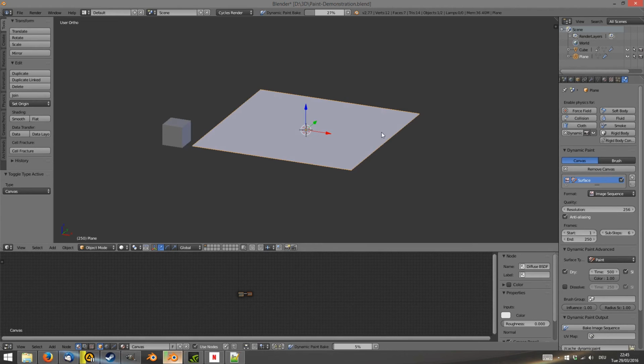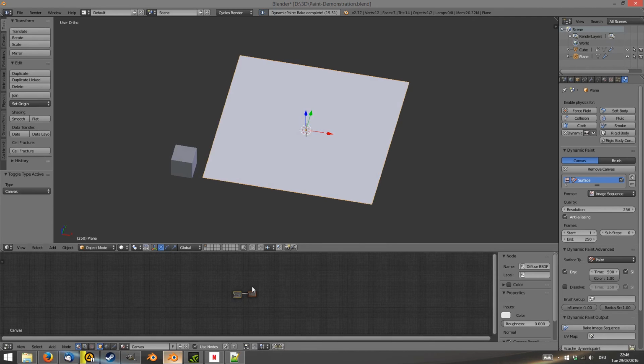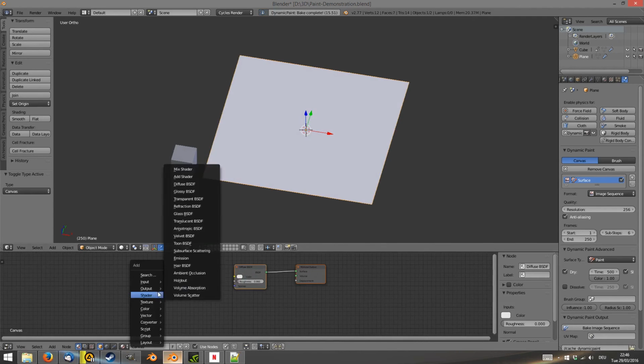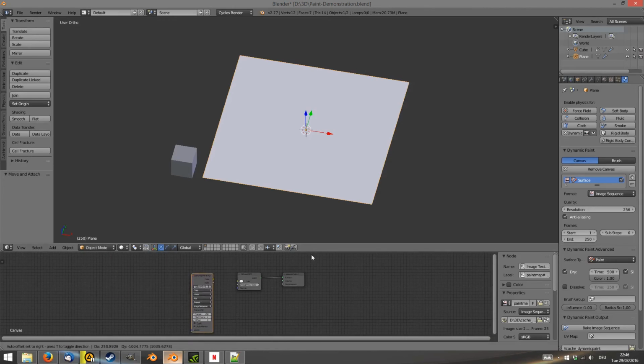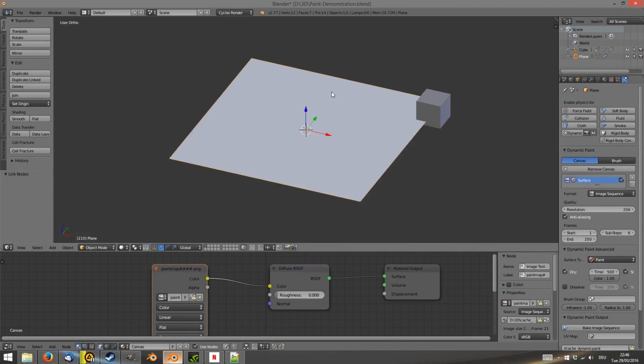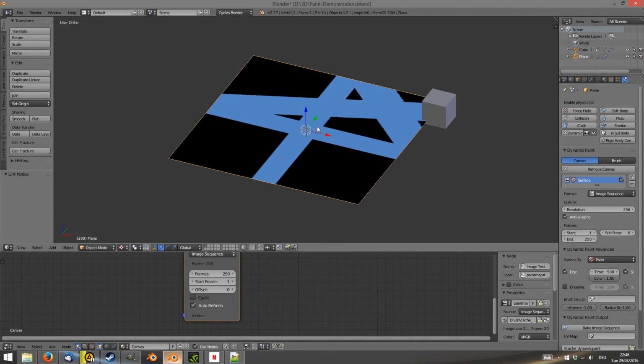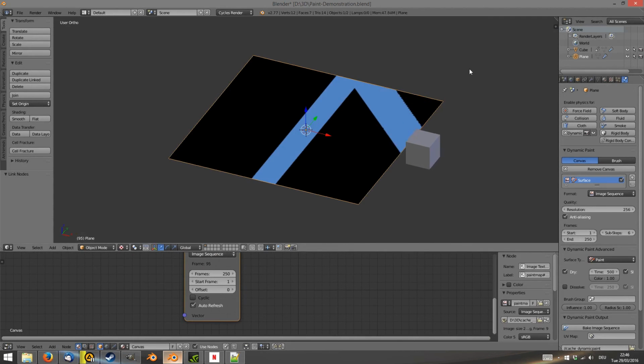The texture resolution for this is set to 256. You can set it as high or low as you like, but it will affect the time it takes to calculate and the required storage space, since it saves 1 image file per frame. Now that it's done baking, you have to set up the material. In cycles, this is done using the image sequence texture. Selecting auto refresh updates the texture automatically as you move between frames in the editor. It is not necessary for rendering.